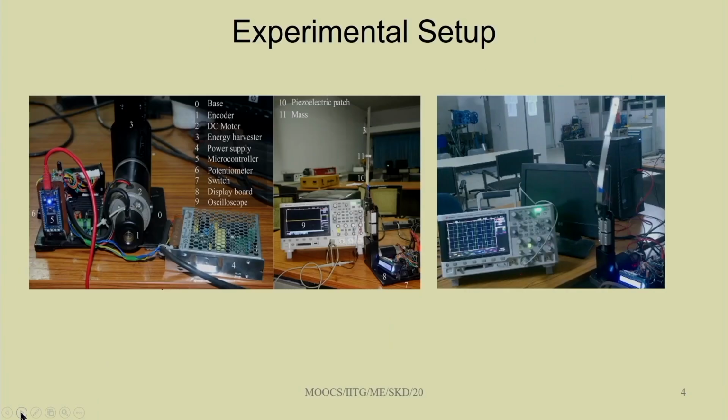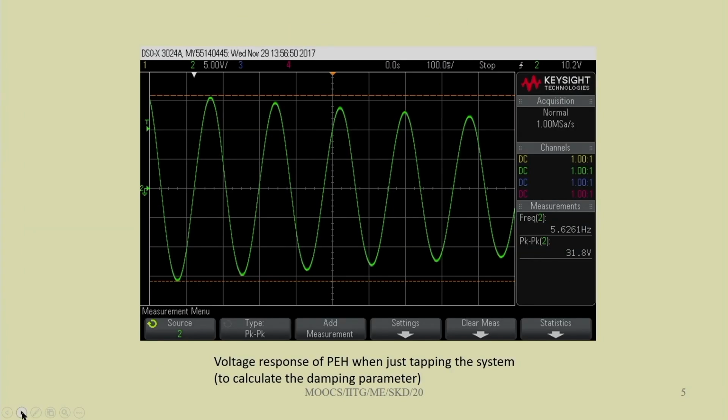In particular, in the case of parametrically excited systems, we have seen this example, that is a base excited cantilever beam. When the base is moving up and down, we can see the cantilever beam will move in the transverse direction. Here the application of force and the direction of motion are taking place in perpendicular directions. That is a typical case of a parametrically excited system.